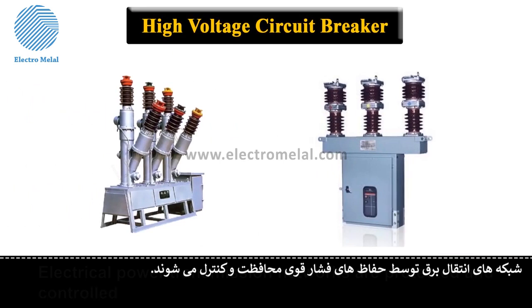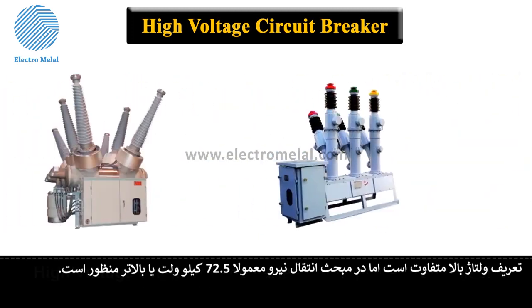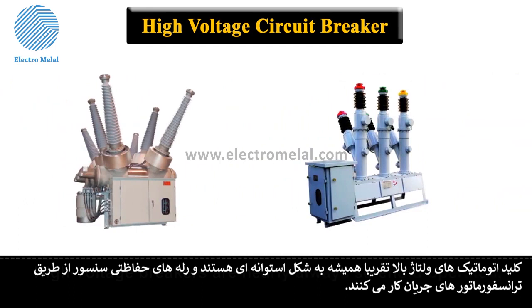High voltage circuit breaker. Electrical power transmission networks are protected and controlled by high voltage breakers. The definition of high voltage varies, but in power transmission work it is usually thought to be 72.5 kV or higher. High voltage breakers are nearly always solenoid operated, with current sensing protective relays operated through current transformers.